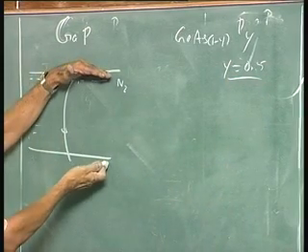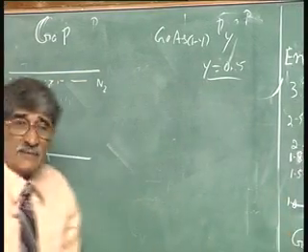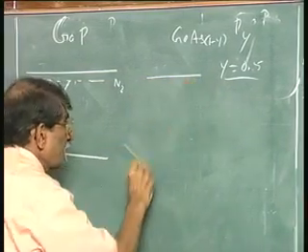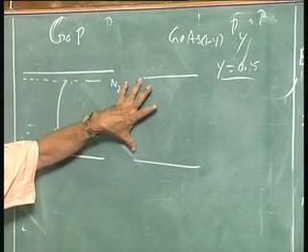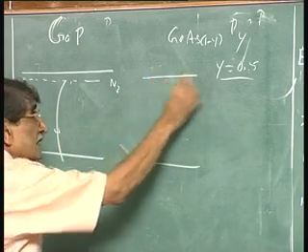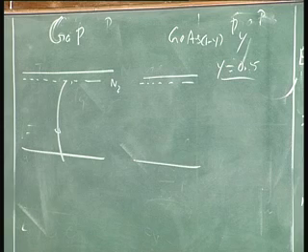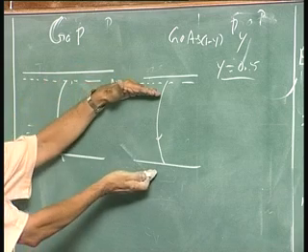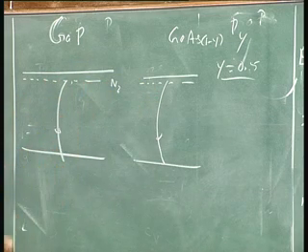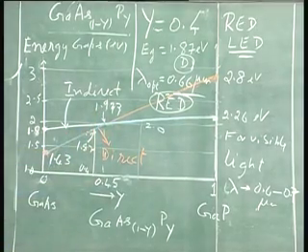Then what happens to the band gap compared to here? The band gap is reduced, so that is somewhere here. The nitrogen level practically does not change, the difference between the two. So, if the band gap reduces, nitrogen actually enjoys the same position, practically 0.05. So, the transition now is from here to here, which was that much, and now has reduced. Energy has reduced, which means the wavelength has gone up. You go down here, you go from green to red.